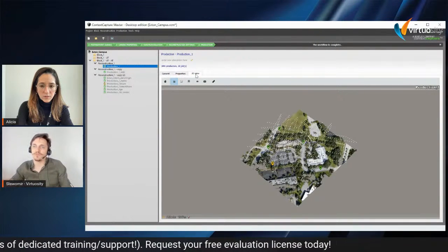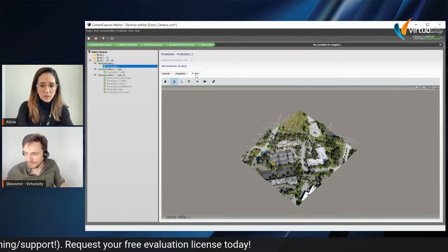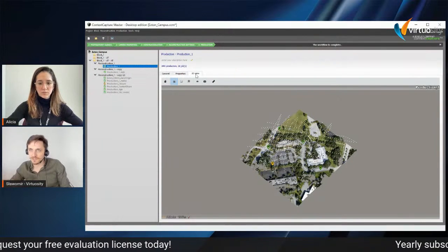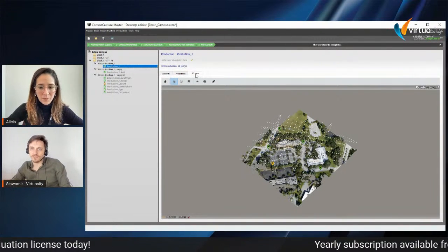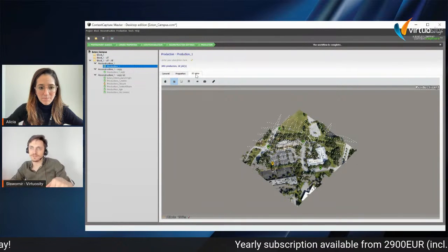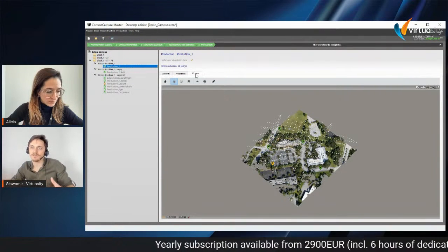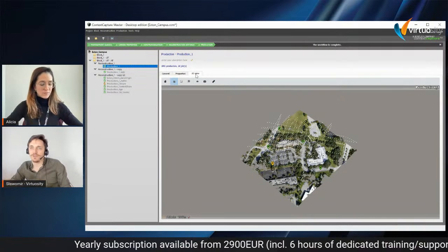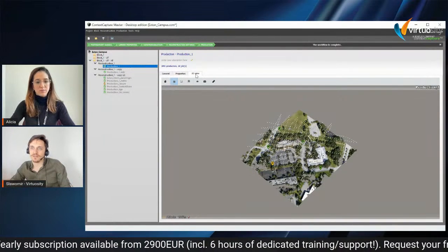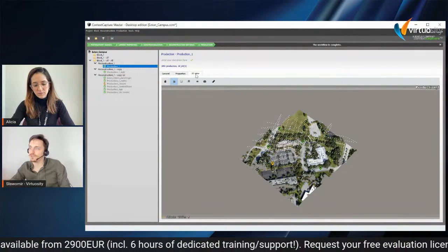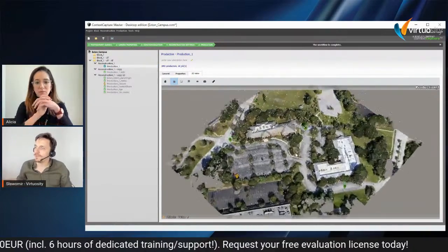This is also possible when we are importing ground control points coordinates. We can import them together with the column for horizontal and vertical accuracy, which is also included in the equation at the end in the accuracy analysis. So really nice feature in my opinion.